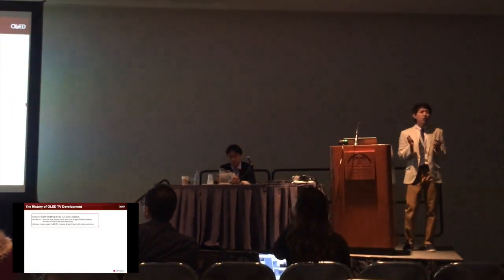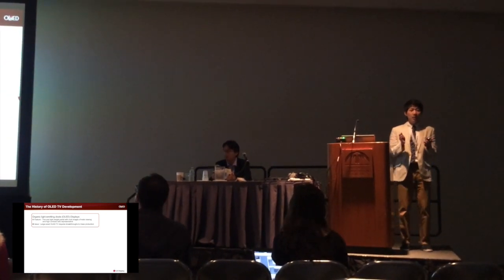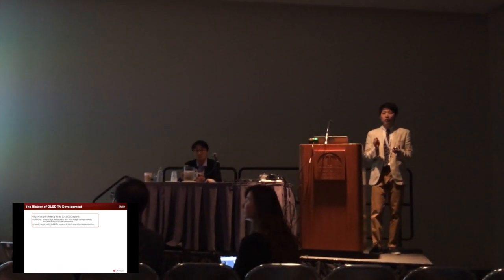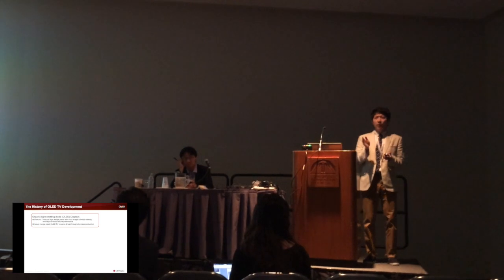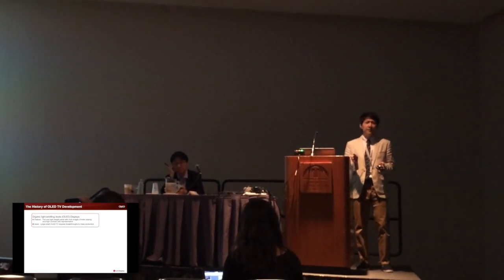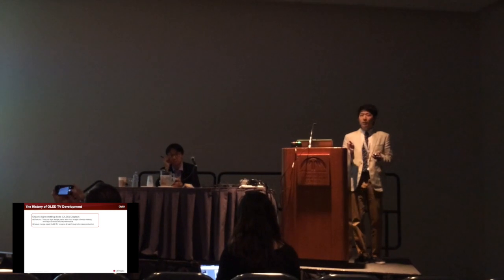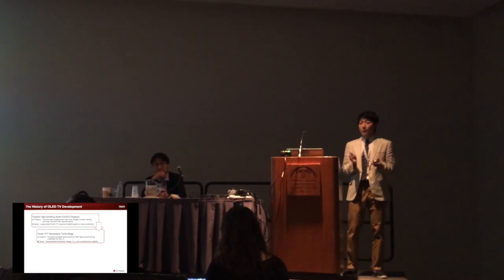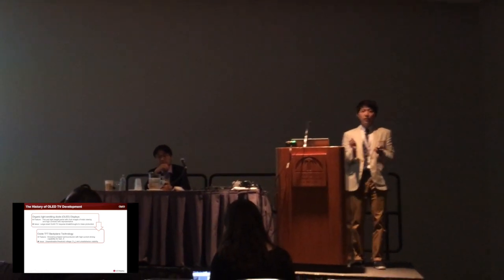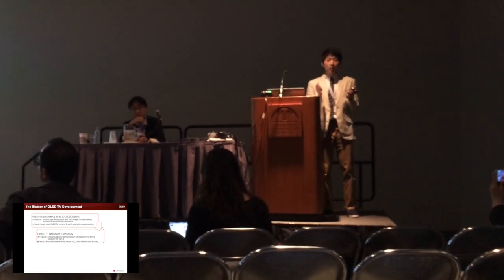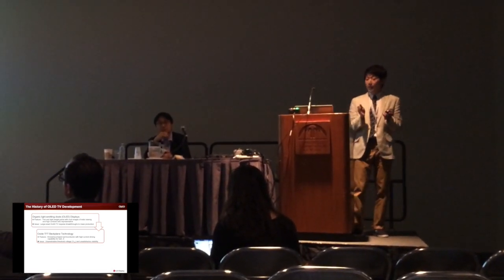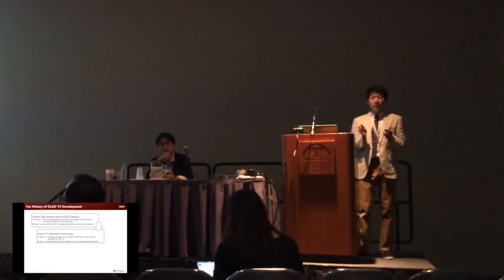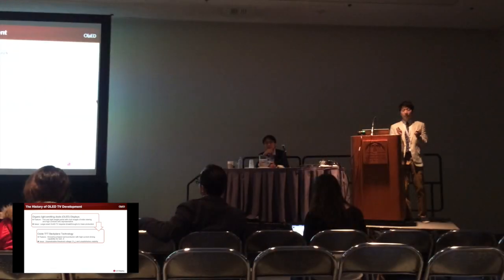OLED display is very suitable as a future display because it's a thin and lightweight panel with vivid images of wide viewing angle and high contrast ratio. But it's difficult to make a large-size OLED TV, and it requires a breakthrough for mass production. Oxide TFT backplane technology is a very good solution for this problem. It's an amorphous-based semiconductor with high current driving capability for Gen 8. But there are issues such as unpredictable threshold voltage and unsatisfactory stability.